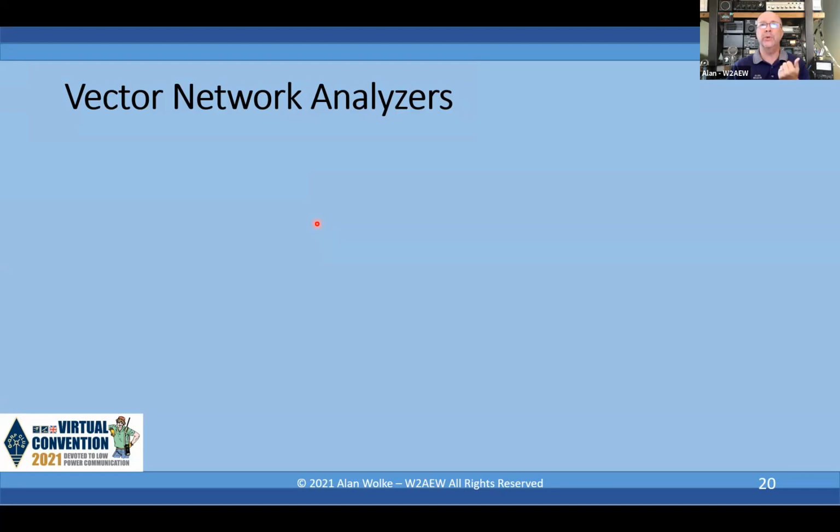What precautions do you take when checking harmonic levels from the transmitter? I'm going to talk about coupling signals in at the end of the talk, with things like RF samplers, so we'll deal with that then. A return loss detector can be frequency sensitive, and that's why, again, a normalization function can help. Spot on what I was asking for.